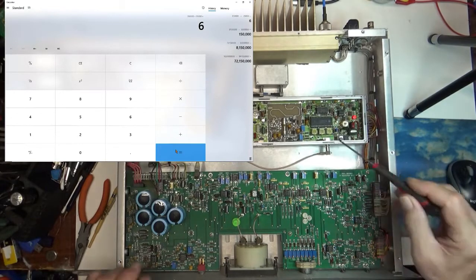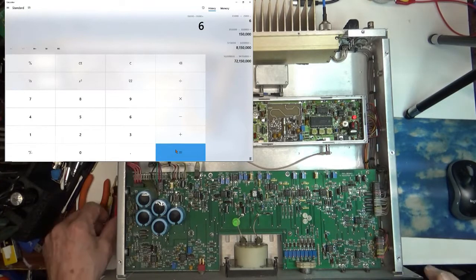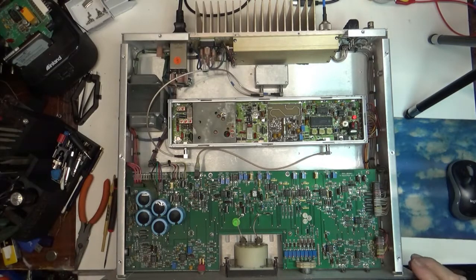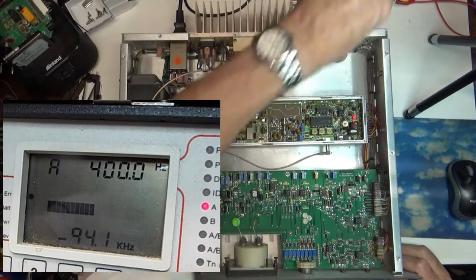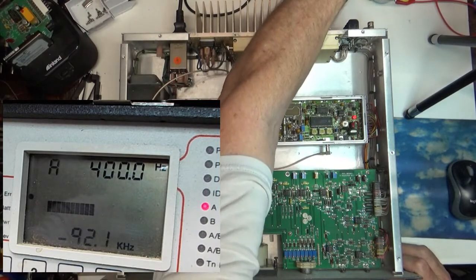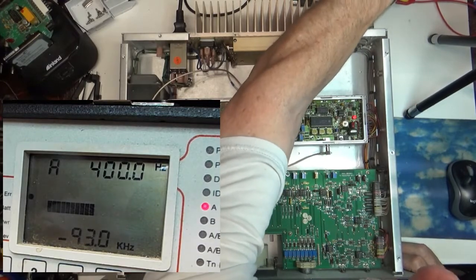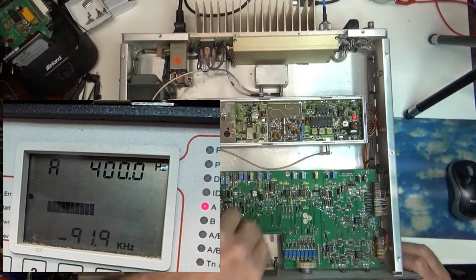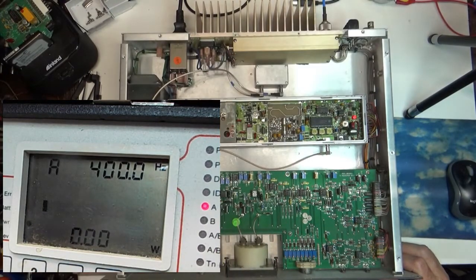All right, so 2, 0, 6. Okay, to start with on 6, we turn on the transmitter. Well, first of all, turn it off. Set the frequency to 947.850. Enter. Turn on your transmitter. Go to power. We got nothing. No power at all. Why?